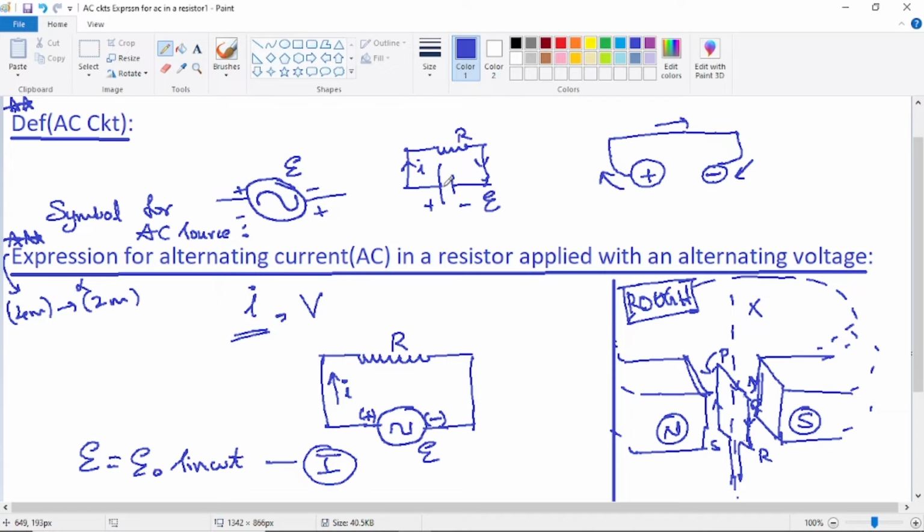The electric field is called a conservative field because the work done depends only on the initial and final positions, and is independent of the path taken. Based on this conservative nature of the electric field, Kirchhoff's voltage law is derived. Just check the derivation of Kirchhoff's voltage law. Directly it comes from the conservative nature of the electric field.